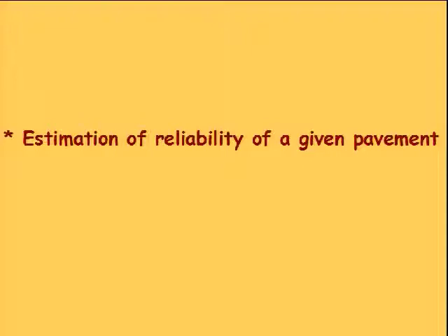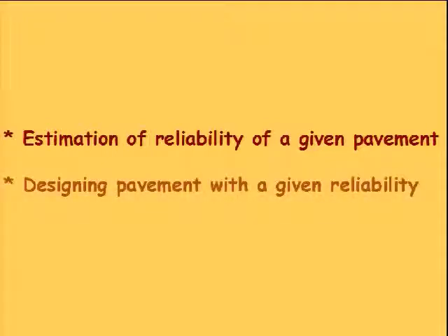That does not work well for a pavement structure, given that the analysis of the pavement is very complex, where elastic modulus, thickness and tire pressure are the inputs, and you are getting the number of repetitions it can sustain as output as a distribution. So most of the time we end up doing a kind of simulation run where we estimate the reliability of a given pavement. But the second part of the question is more difficult, because you are going to design a pavement for a given reliability.